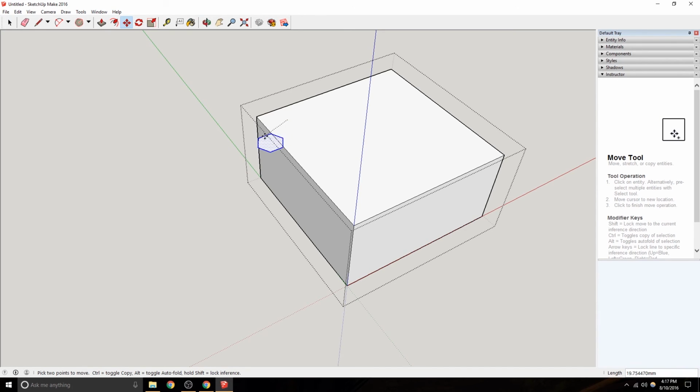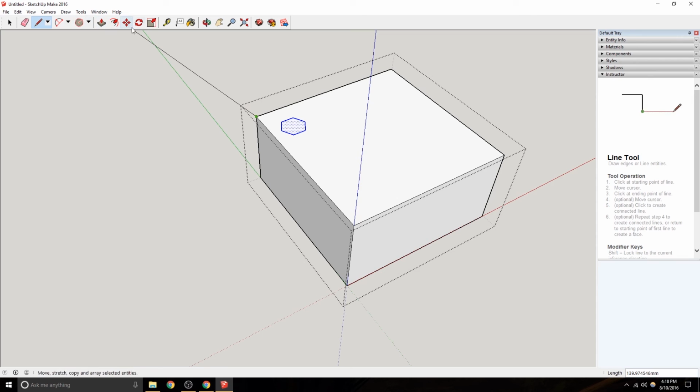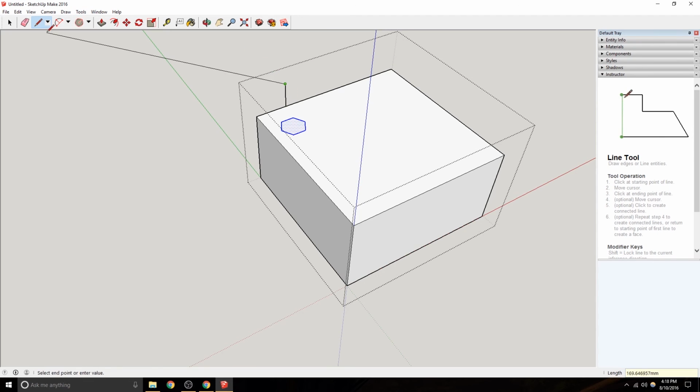You can either, if you do this and then pull back, it can create problems. It's trying to attach to this line. So escape, Control Z. So oftentimes to align things, you either have to use a ruler tape measure function, or you can say I want this to be, let's say, 20 out. So it's going to create a little anchor point there, right?